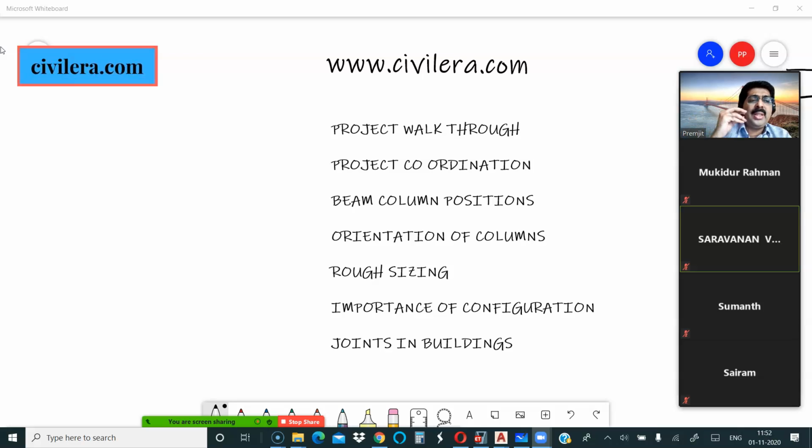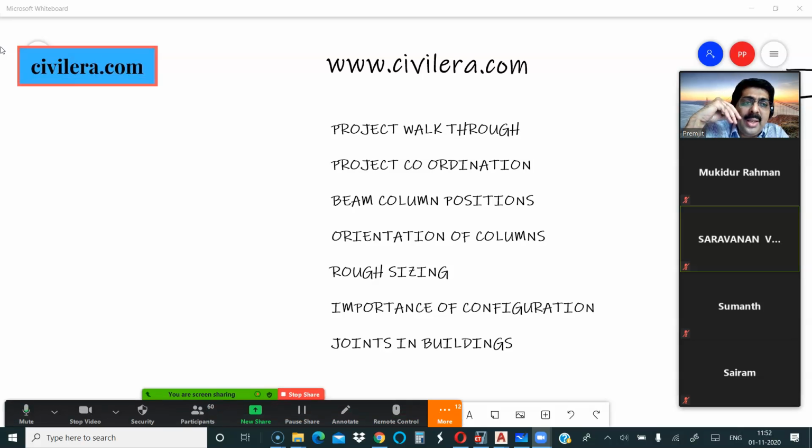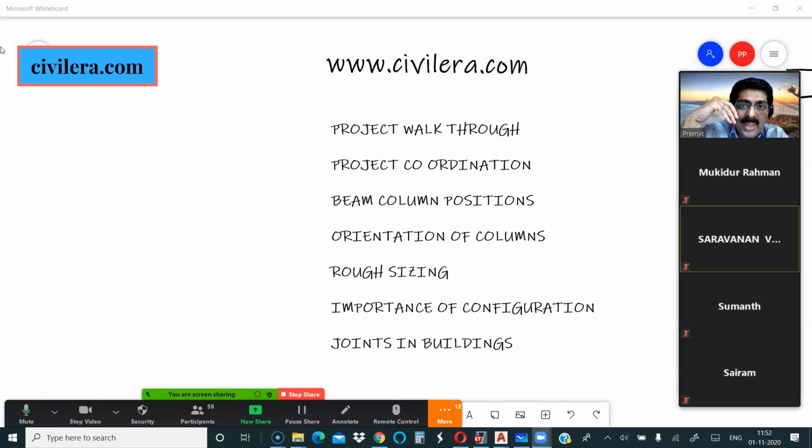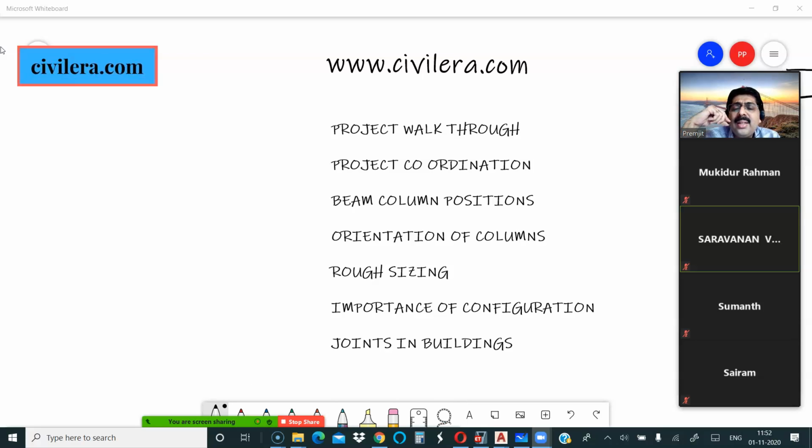There are possibilities in ETABS. You can do temperature load analysis, and if the increase in stress is taken care of by reinforcement, you may not need joints for expansion reasons. But the joint that I mentioned today is about joints that are needed to make your irregular building into regular buildings. Did that clarify?